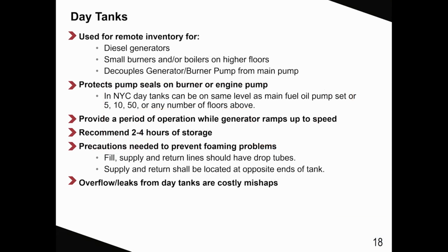Day tanks. Day tanks are used for emergency generators, boilers, and other fuel burning devices. Used for remote limited supply at the fuel burning device, and decouples the appliance pump from the main transfer pump on the bottom floor.